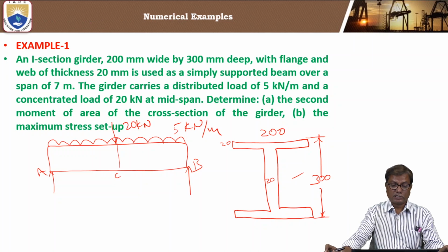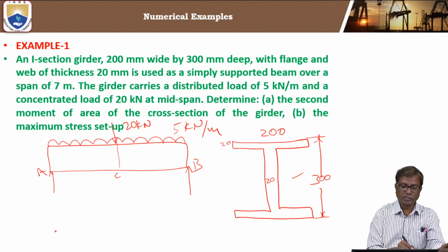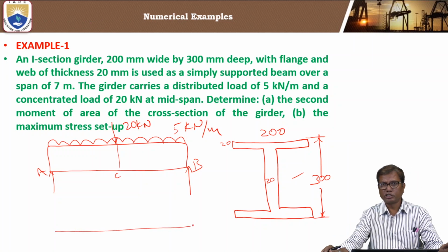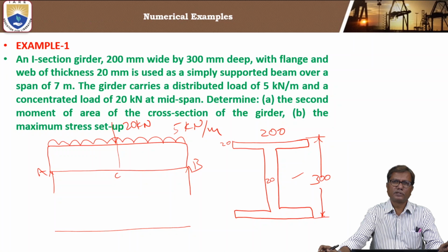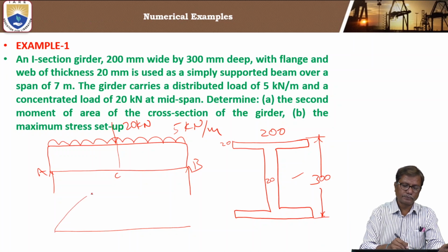In a simply supported beam, the maximum bending moment will be at the midspan. For the given loading, the maximum bending moment will be at the midspan.